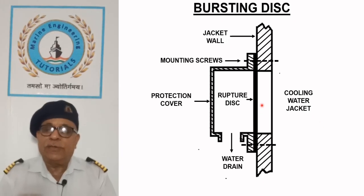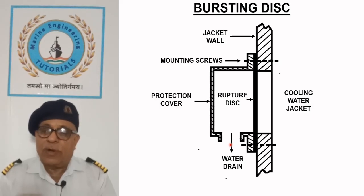When the disc ruptures, the protection cover directs the water downward and prevents damage to nearby machinery or injury to operating personnel. Bursting disc ruptures at the set pressure and must be renewed after the tube leakage has been rectified.